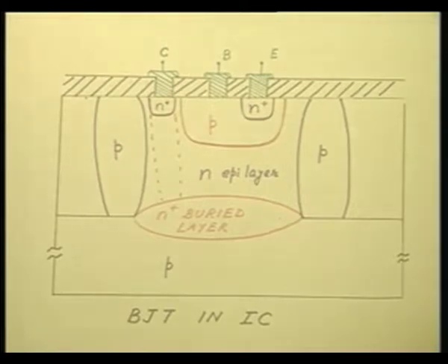The other drawback is of course, you see this junction isolation is p-type, okay, and my base is also p-type, and in between I have the collector N region. So, along with my vertical NPN transistor, I have a parasitic PNP transistor comprised of the isolation, the collector and the base of my active transistor.